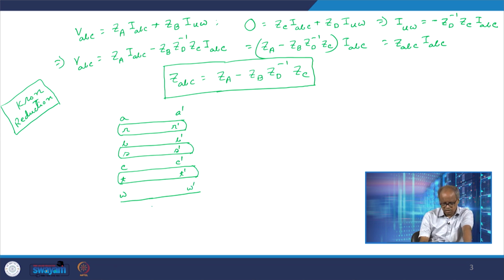So now there are 7 conductors. We will first write down the 7 conductors equation by using a 7 cross 7 matrix. And then we will take the current of phase A as IA plus IR, phase B current as IB plus IS, phase C current as IC plus IT, and this current is IW.